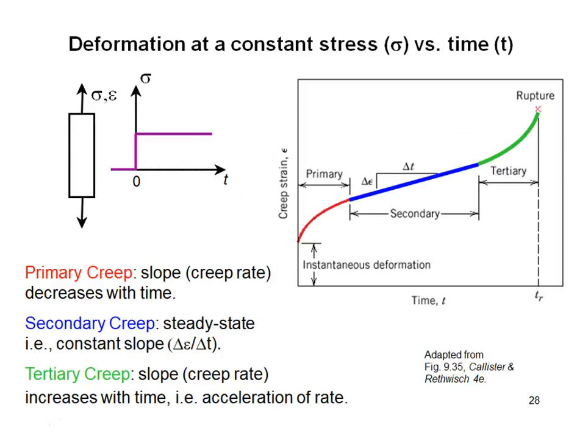Okay, just like fatigue, we can quantify the rate of creep, so we can get some prediction of how quickly a material will fail, how tolerant we are, because everything does creep. So we can't totally preclude it, but we can design around it and see how long it will last. So if we are looking at a material that is subject to a constant stress, as opposed to a constant deformation, this is the creep mode, not the stress relaxation mode.